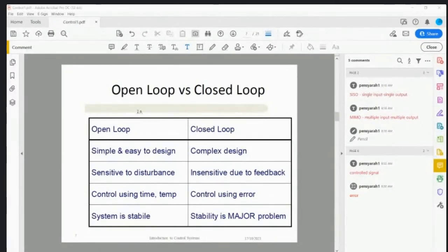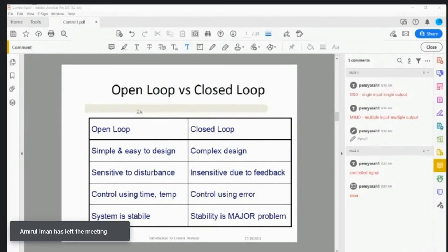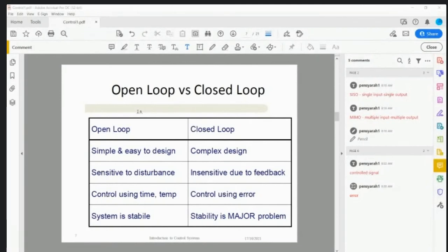So the sensor will tell the controller, the system, that the temperature is not yet 24, because of the open windows. So the temperature is not 24 degrees Celsius. It feeds to the controller, which will compare it to the input, so the controller will know what to do.